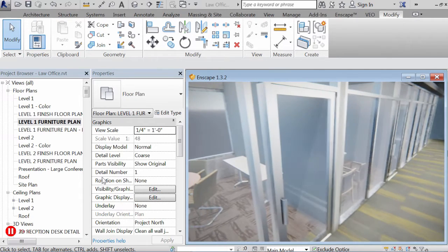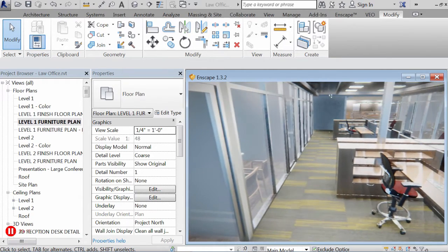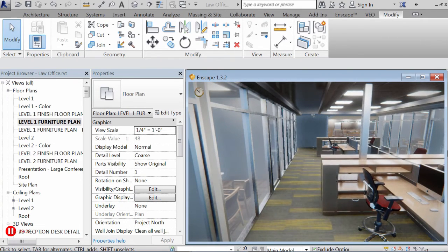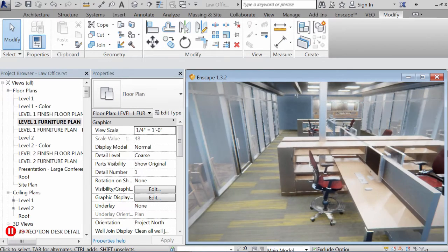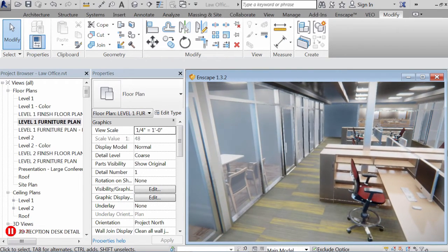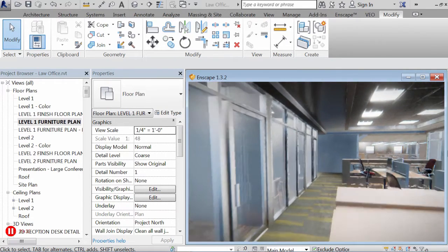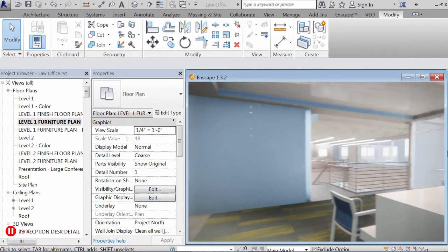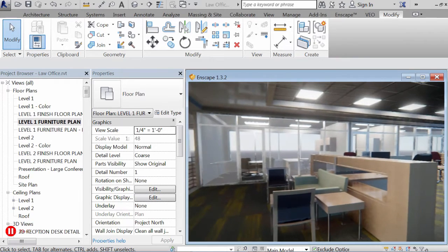Yeah, I think it's pretty straightforward. You don't have to go back and repath everything. It's just looking for the material by name. Right, and that's assuming it can find it. If it's in some obscure location, then you have to go into Revit's options dialog box and point it to that area. And then when you do renderings, whether local or in the cloud or using Enscape, it'll actually be able to find the material.